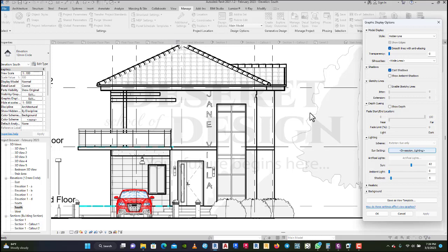Okay, so you can do this. You can set it like this, neatly done. Now when you go to realistic, realistic means that if we were doing modeling, we change the model view. If you have changed the model view to realistic, this thing will be active for us, to control how dark or how bright we want our realistic. But since you are using hidden line, it is not active.